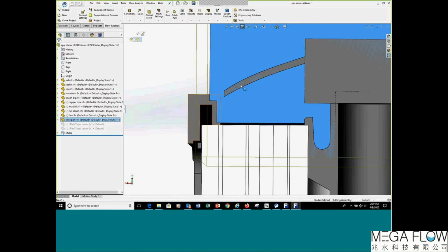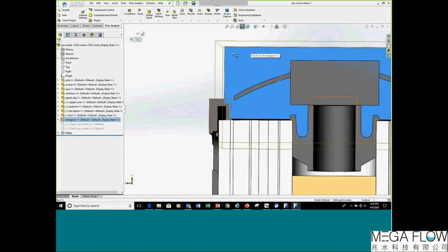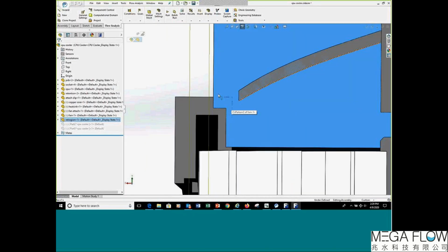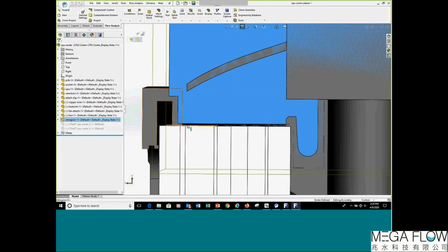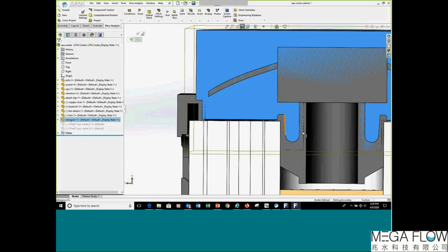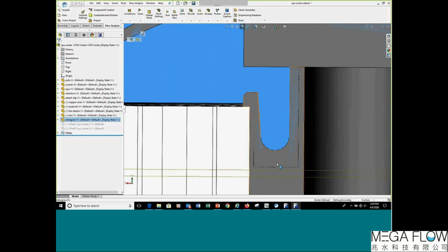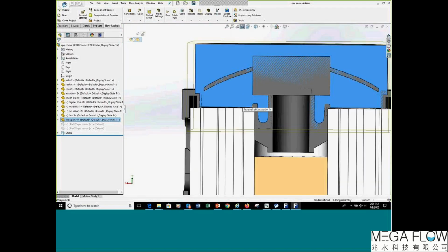So for that reason, they created the rotating region a little larger, and they purposely embedded it into the solid of the attachment clip here, okay? So it embeds into the solid, and then in the horizontal position, it's in the fluid break just between the heatsink and the fan blades, and then it embeds itself again into the solid of that fan attachment, the hub, okay? That's the 2D sketch that was revolved.